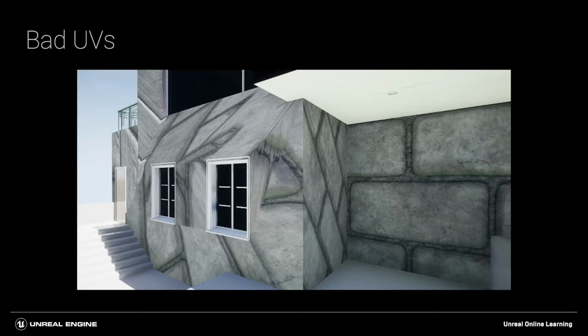If you create a 3D model in your 3D modeling program and you don't create a UV map to use for materials, you may notice that textures applied to the model may be rotated, scaled, or have visible seams. Notice how the materials on these walls are noticeably misaligned. I did not create a UV map for these objects. The UVs for these were automatically generated.